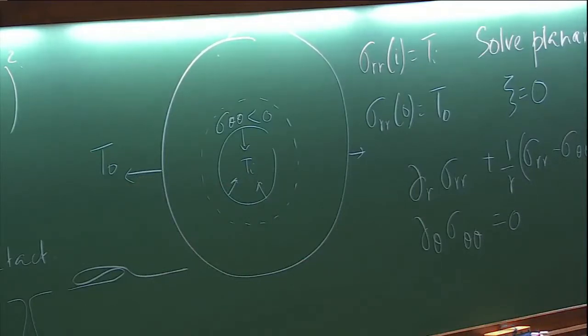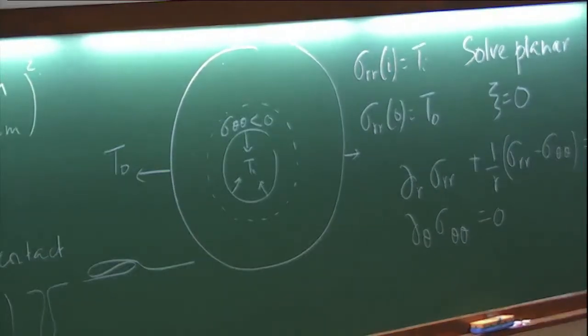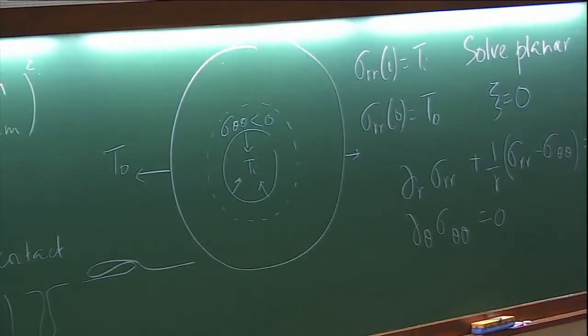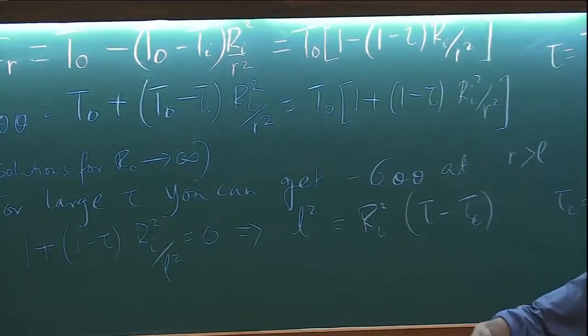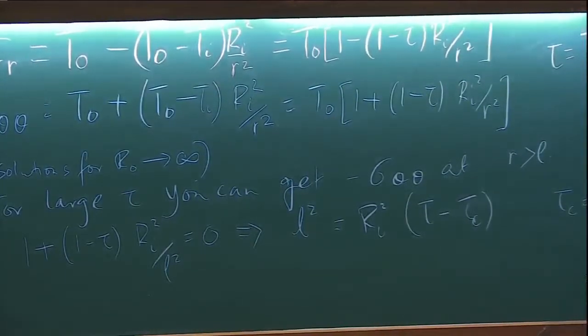So in the Euler buckling problem, this is when you first start with non-zero delta over W. Okay? Doesn't mean you'll immediately see wrinkles. You don't get Euler buckling with 0 onset. This is what you will see. This will be the length of the wrinkles if the bending modulus was 0. If you have infinitely flimsy material, as soon as you compress, you maybe start seeing things, okay?